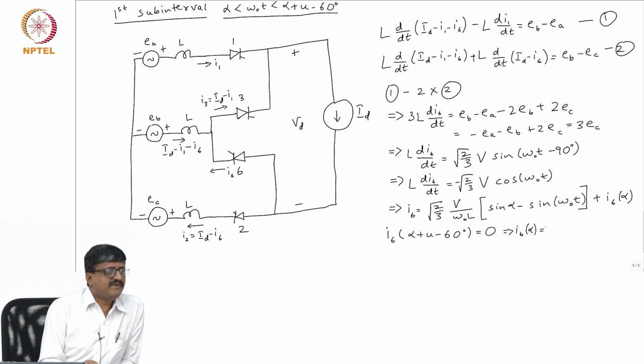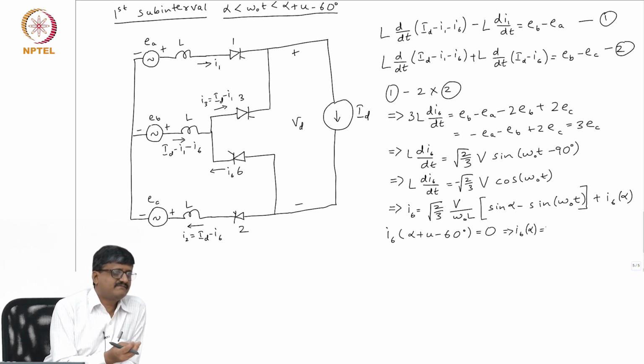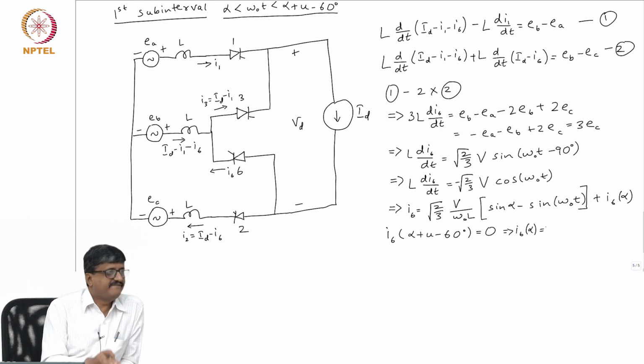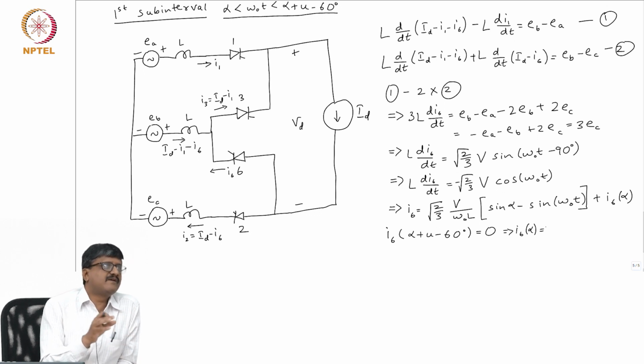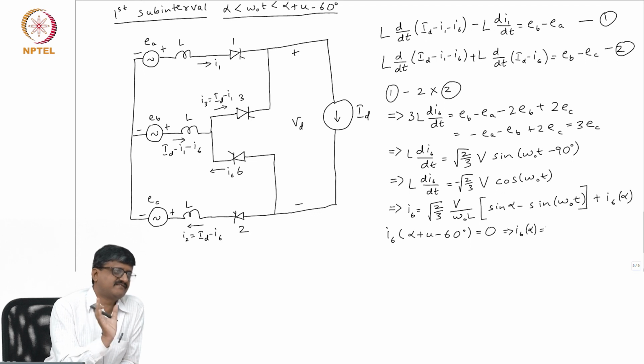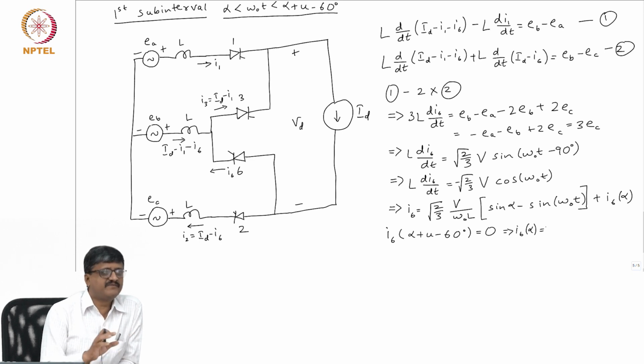Abnormal operation may exist for a few seconds or a few minutes in a year. So, for abnormal operation, we are not going to minimize harmonics. It is actually not eliminate harmonics, minimize harmonics using filters. Filters are designed to minimize or reduce harmonics. So, we are not going to worry about abnormal conditions which may exist for a few minutes in a year. What we are bothered about is normal operation. So, harmonic analysis is done only for normal operation, because we are going to design filters only for normal operation, not for abnormal operation.